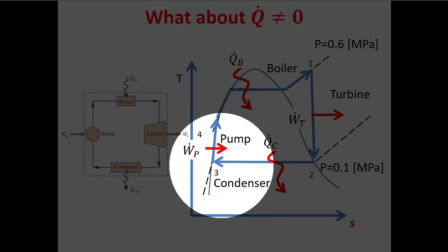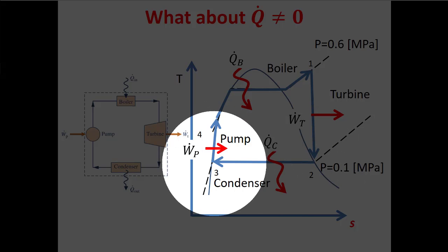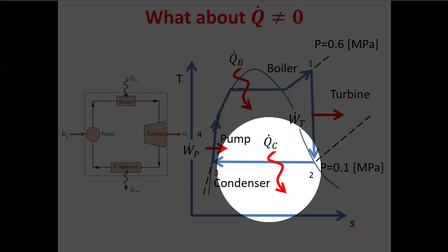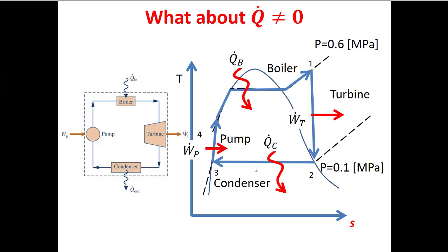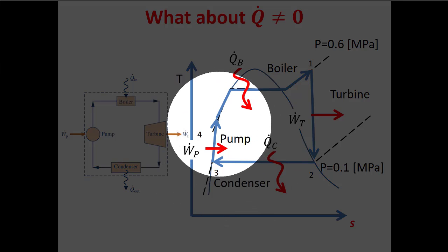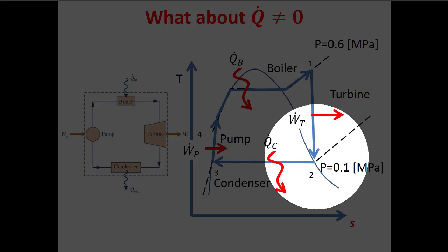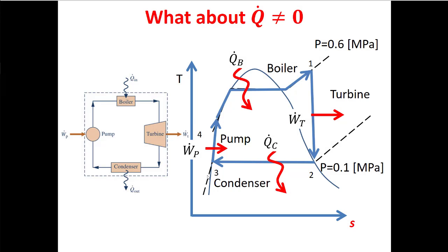So in the condenser, we go from a vapor down to a liquid. And we can see pretty clearly, this is a TS diagram, S is decreasing. S is increasing everywhere else on this graph. This is a real pump, so S is increasing. The boiler, certainly S is increasing, we're moving to the right. The turbine, down and to the right. But then this condensation reaction, entropy is decreasing. So how can that be?